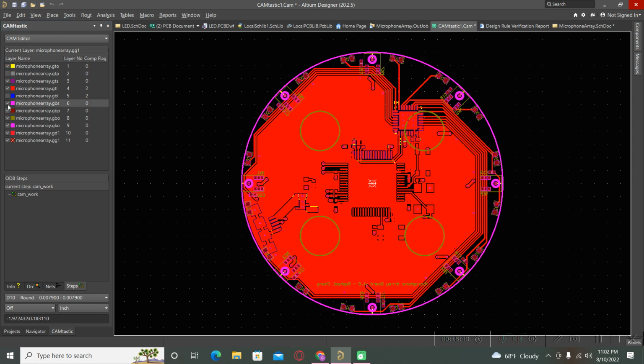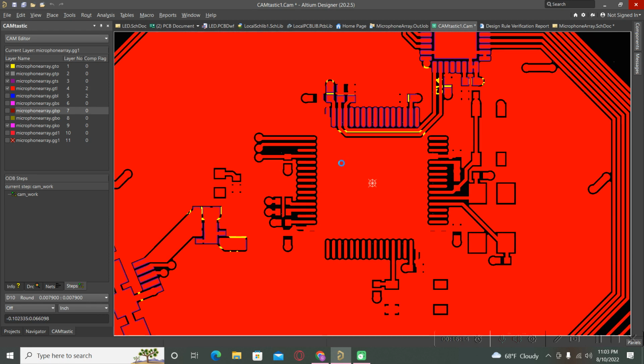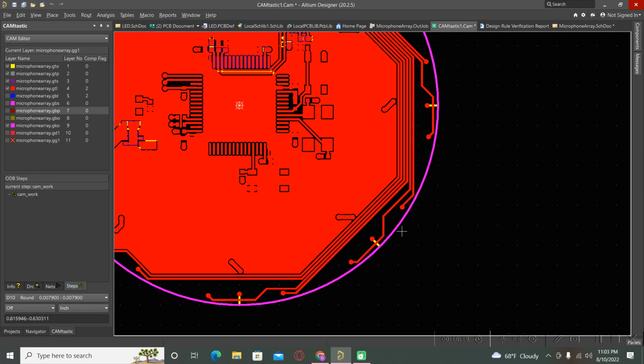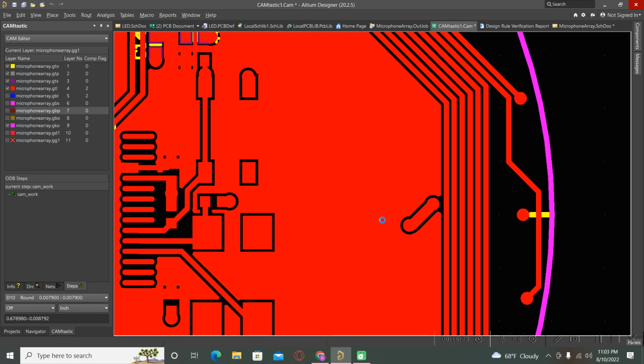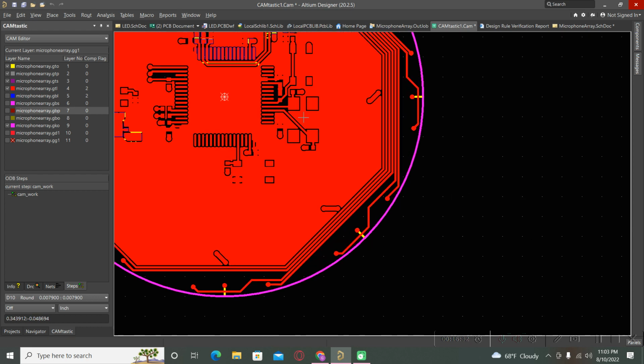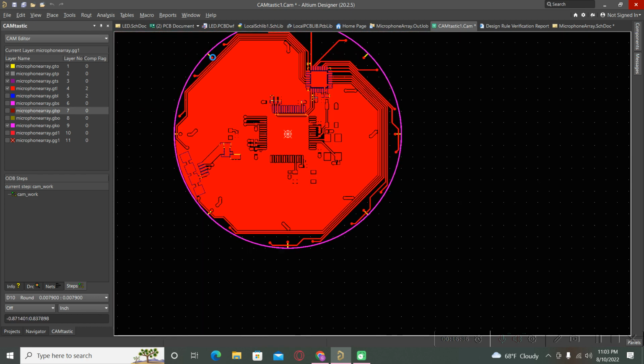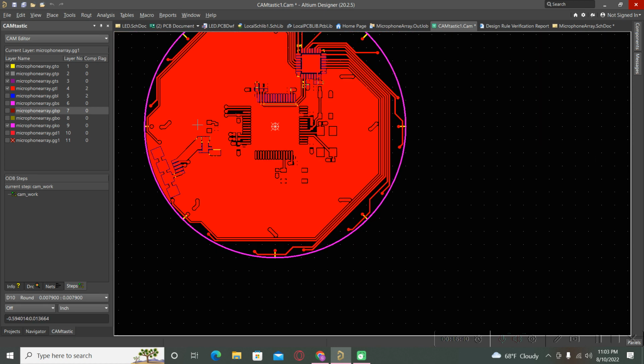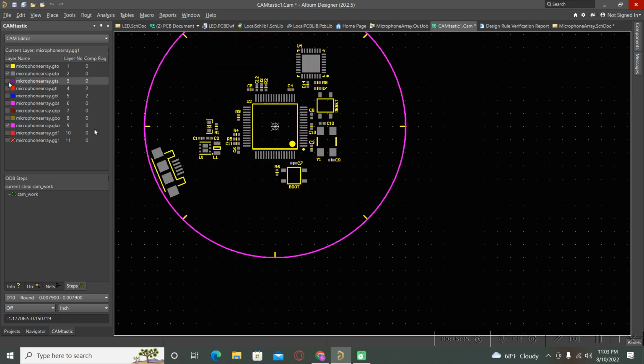we can turn off all the other layers. And now we can simply check for the top layers if our layout looks okay, or we still need to do some modifications, or maybe sometimes the clearance is not enough, and we can simply check this in this view of the Gerber files, and we can leave only the components and the paste and the top overlays.